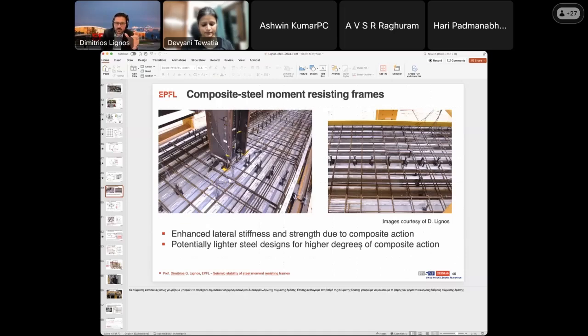Now, based on the work that we've done, and also based on the review of the available tests on inelastic deformations in the panel zone, if you go up to about, I would say, 6 to 10 gamma Y, it should be okay. But you should also have in mind what is the corresponding drift level that we would like this to happen.